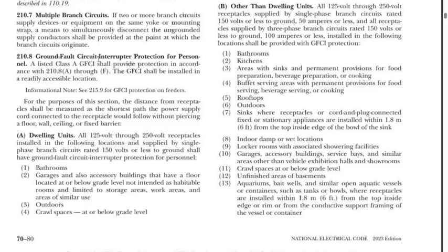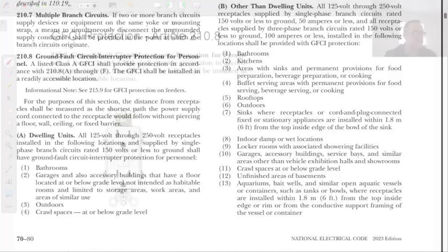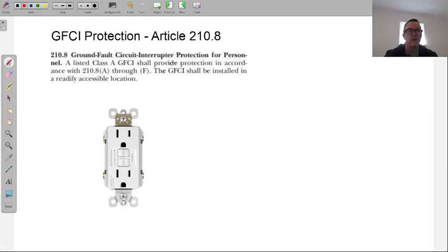But there is a common sense theme around GFCIs, and that is water. Everything you see in both of these sections is related to either water or places that can get flooded. That's the general theme around GFCIs. GFCIs get used anywhere near water.